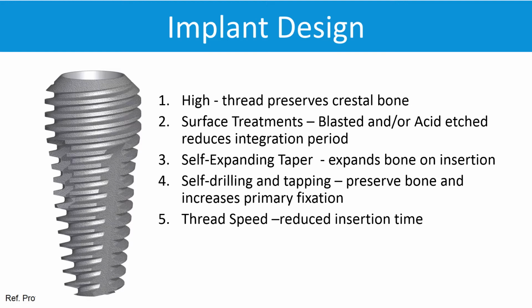Now in order to be able to achieve this, the space between the threads, or the thread pitch, needs to be quite wide, say 10 millimeters, or I'm exaggerating now, more like 1 millimeter between the threads would advance. It means that if you turn the implant 360 degrees, then that implant will be inserted into the bone by 1 millimeter.